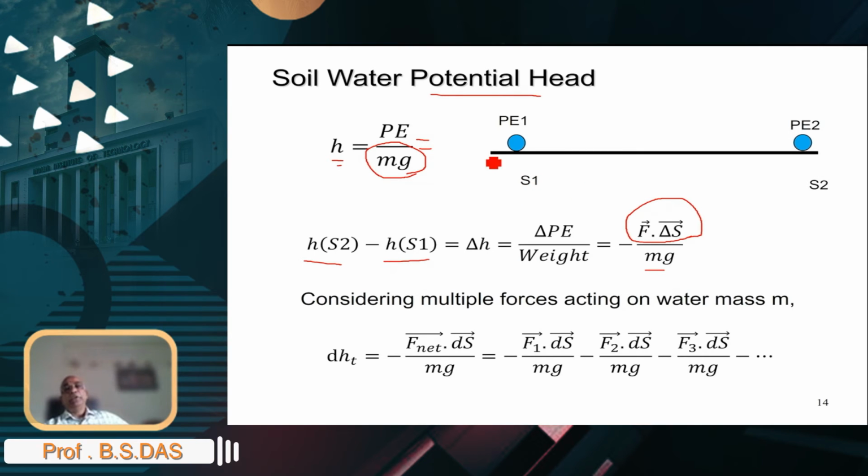And of course, you need to really think about the kind of forces that are acting on the water. As we discussed earlier, you could have at least four different kinds of forces when it comes to contact between water and soil or water and solute. And we said that at least the osmotic and the capillary forces would be involved. So think about, and we know that water is also being pulled downward because of gravity. So the gravity would be another such force.